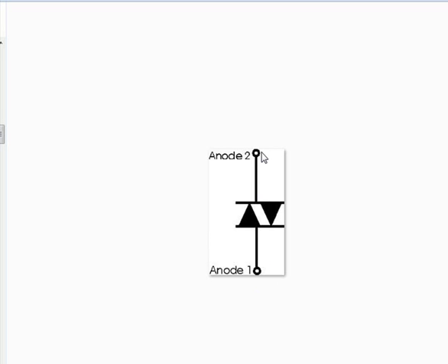A diode doesn't conduct in both directions. This conducts in this direction, and this direction also, provided the voltage level at which it is manufactured is crossed, and that is what the Diac is. And it's not easy to check the Diac with a simple multimeter.